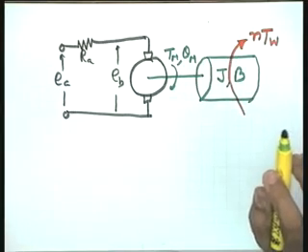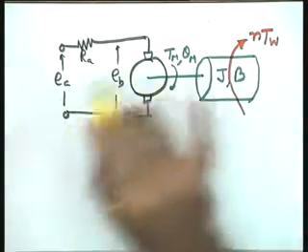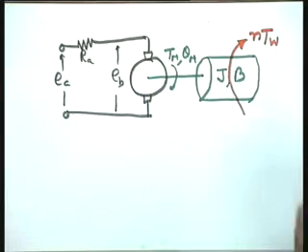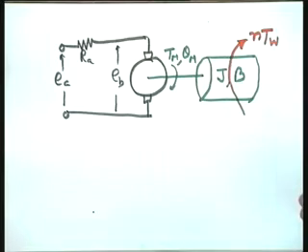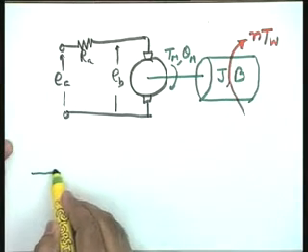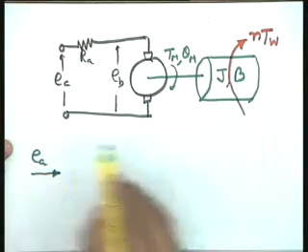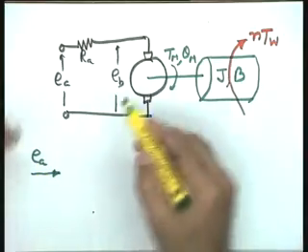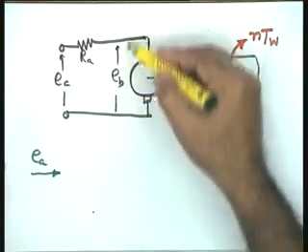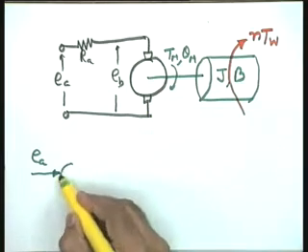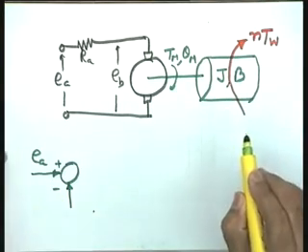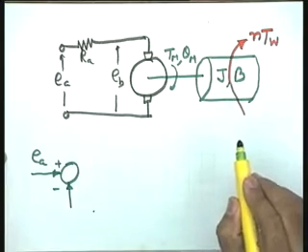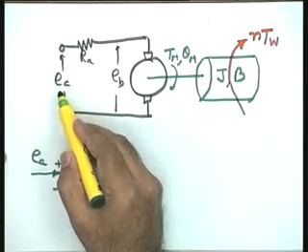I tell you that after some time you will really not require the differential equations. You will be able to write the block diagram model directly from the schematic diagram of a system. Make an attempt here itself. Just see that your input is EA, the armature voltage, and this is being opposed by the back EMF, and therefore, let me use an error detector here to represent this particular phenomenon, that is, the back EMF opposes the applied voltage.